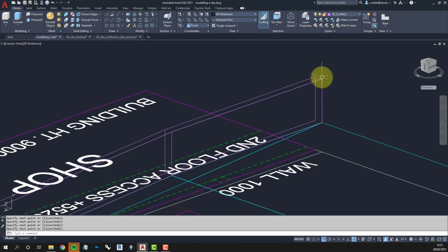So what we could use here is the change command from the keyboard. So -CH, enter. I'll just pick one of them to use as an example. Enter. It's a property, it's thickness, and you can pick the thickness now from the screen. Now the direction can sometimes go the wrong way, but it should go this way. So 1, 2, enter, enter to finish.